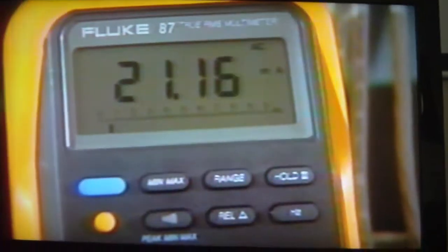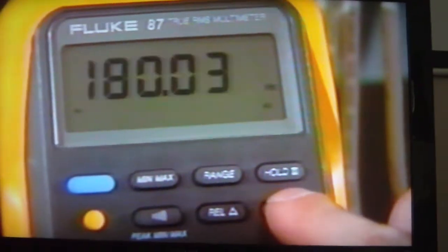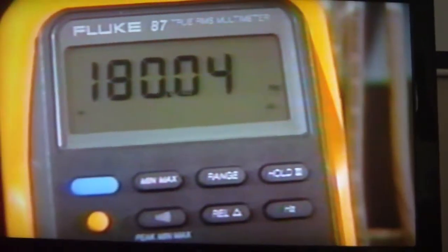Survey the subpanels that feed harmonic loads. Measure the current in each branch neutral and compare the measured value to the rated capacity for the wire size used. Check the neutral bus bar and feeder connections for heating or discoloration. Also measure the current and frequency of all the neutrals. Again, 180 Hz indicates the presence of third harmonic.